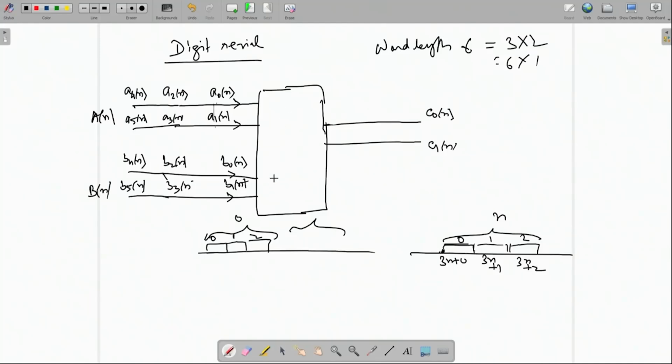Originally, I had 6. By going fully digit serial, I could bring it down to 1. Now I am not bringing it down to 1, I am bringing it down to 2. So, in comparison to the fully serial one, yes, I will pay more in power, twice in fact, and more in hardware. But in comparison to the original one, I am still gaining in hardware, because from 6 I have brought it down to 2.